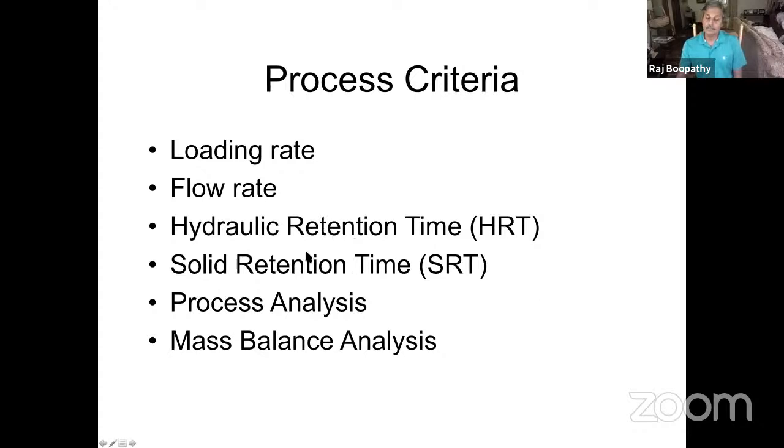The HRT and SRT. Hydraulic retention time is basically the time the wastewater spends inside the reactor, okay? Solid retention time, or sludge retention time, is the amount of time the bacteria, the biomass, spend in the reactor. So when you design a reactor, you need to have a high SRT. You want to keep your bacteria in the system as long as possible, because these are the bacteria removing the carbon. You don't want to lose them along with the treated water. So you need to retain these biological solids as much as possible.